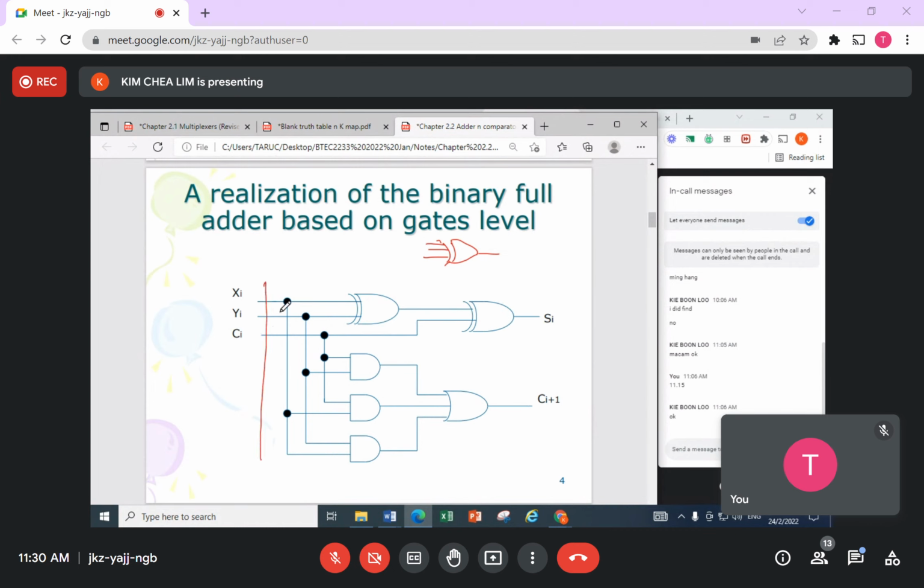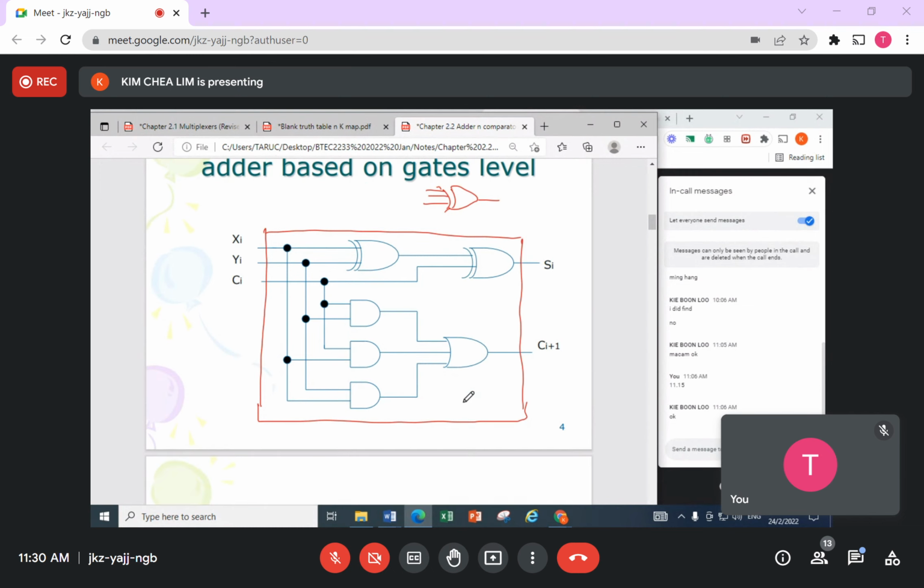So my full adder, just 1 unit by itself, is this one. And a full adder, actually, you can buy it. It's available. Internally it looks like this. We call this a small scale integrated circuit. You can buy it as an IC. This IC is very simple, 3 inputs, 2 outputs. And maybe in this IC you can have 2 full adders in one shot, whereby you can join them to add up more numbers.